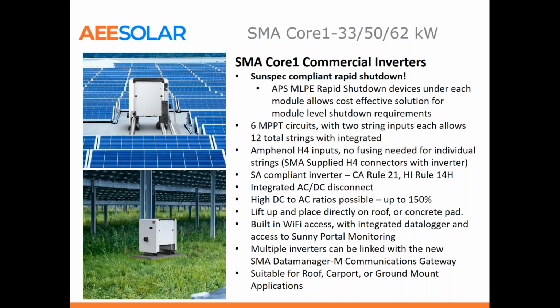There's Wi-Fi built into the inverter, so the data logger is included as well. And then you can also link multiple inverters with the new SMA Data Manager M. So 5 or more inverters would need that Data Manager M to network them. And we've seen these deployed on the roof, carports, ground mounts. Nice inverter, works really well.